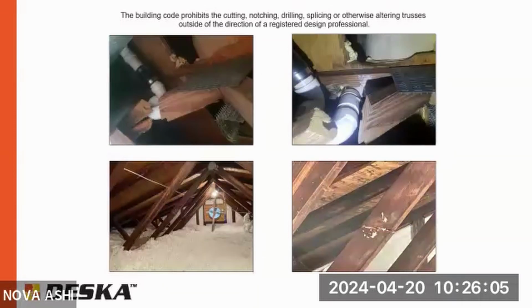And if you walk into a home and you know that your roof trusses run, say, front to back, and you see that the attic staircase is left to right, usually they're about 55 inches or so, and the trusses are spaced at 24 inches usually, they've at least cut one of them. Maybe it's okay, maybe it was modified accordingly, but usually not. Someone just sawzalled it.